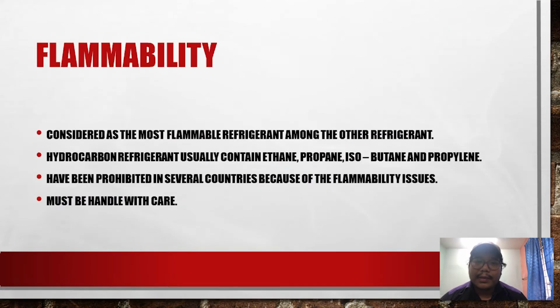The hydrocarbon refrigerant is also known as a flammable refrigerant. This means it is sensitive to any sparks. They are extremely flammable when compared to other commonly used refrigerants like HFC and HFO.